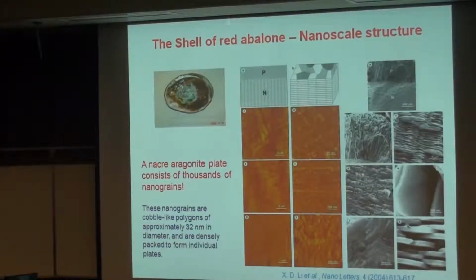If you look at the cross section, you see this kind of brick mortar structure, with a lot of bricks stacked together. And from the top view, you can see this polygonal shape, with the edge length about several microns. People thought previously those bricks are single crystals. They're brittle. The high strength and toughness actually result from the crack deflection along the weak biopolymer interface.